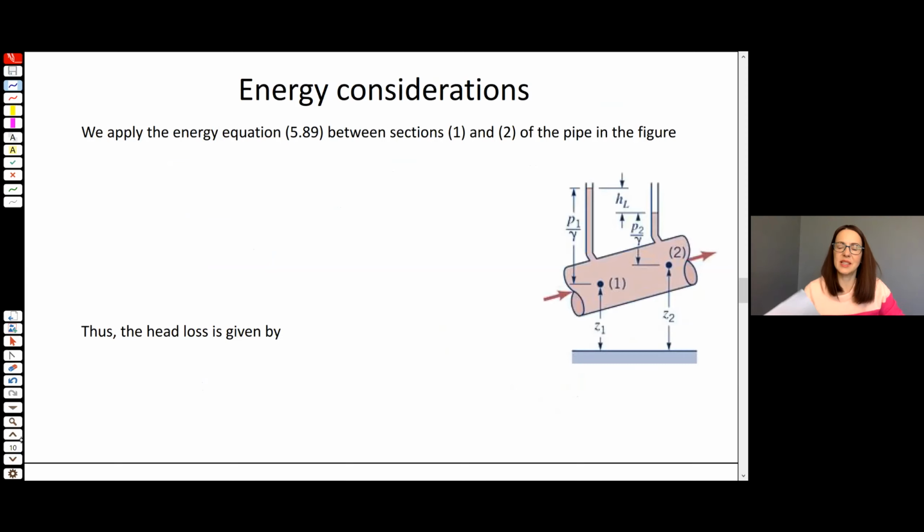All right, one last thing to talk about. For laminar flow through a pipe, we've derived an expression for the mean velocity. We've determined how the magnitude of the maximum velocity, that centerline velocity, relates to the mean velocity. It's actually twice the mean velocity. And we have an expression for the volumetric flow rate Q. We want to just talk about losses in laminar pipe flows.